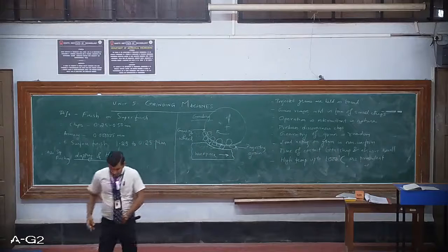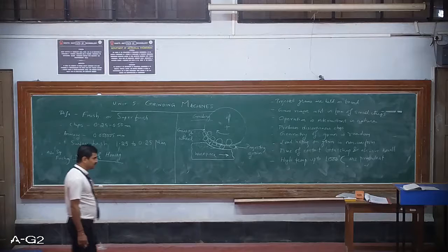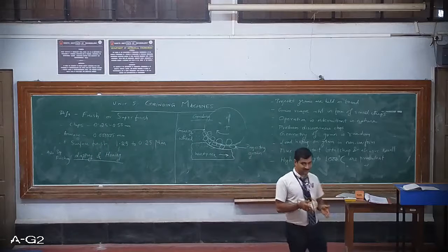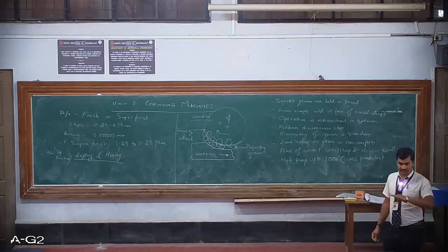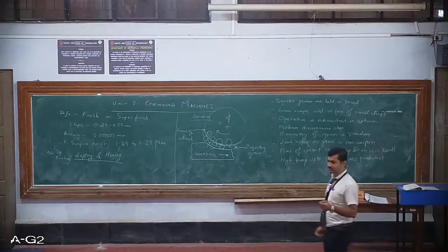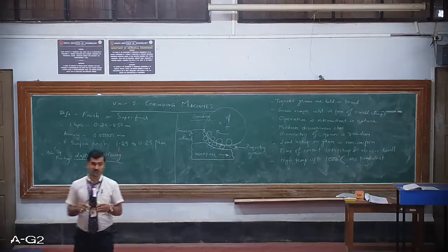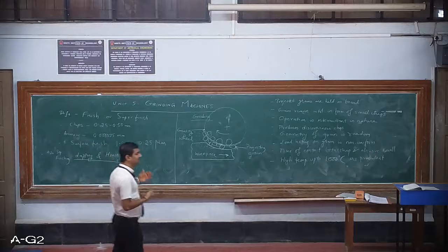Grinding is a metal cutting operation, which we also call a finishing operation, utilized to remove material from the work surface in the form of fine chips by bringing an abrasive wheel in contact with the work. So, what happens between the abrasive wheel and the work?